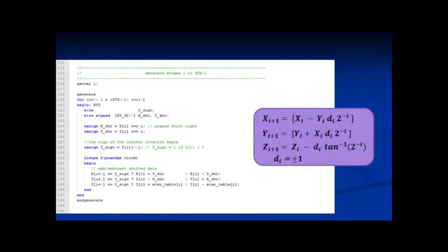In line 133, we see that the next value of x is determined by the calculation that follows. Notice it tests the sign of z sub i. If z sub i is 1, then the angle is negative, and the value of d sub i will be equal to minus 1. Notice it uses this to determine whether to add the y_SHR or subtract it according to the algorithm. Similarly, the next value of y is calculated, and finally the next value of z is